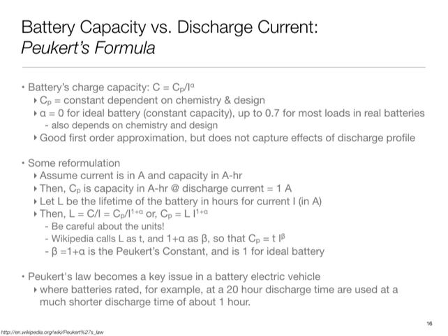Sorry, one more question. Is the I there nominal, or is the I the actual current, and it is in amps? Unfortunately, the way this formula is defined, there is an implied specific unit associated with these things, because Cp is defined as the number of amp hours when the current was 1 amp. So that's how Cp is defined, and then everything else follows from that.